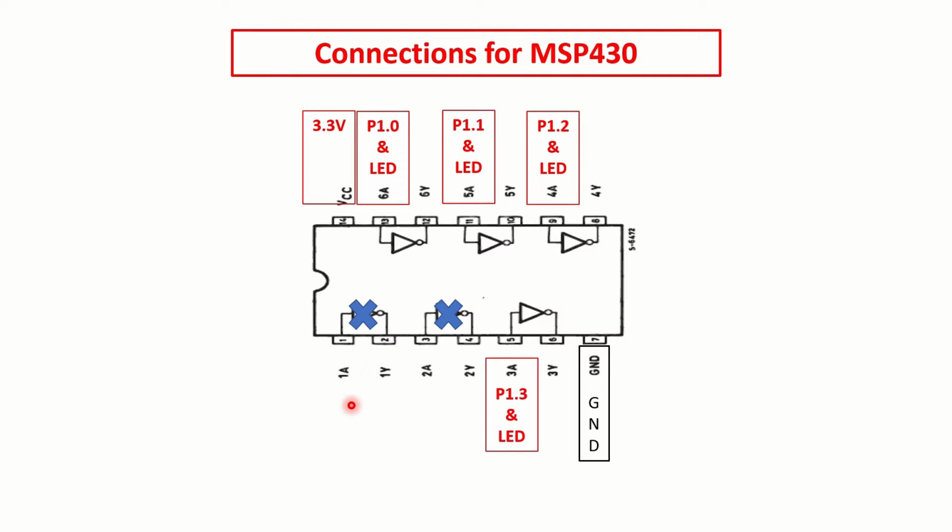I'll be connecting the 4 pins of the P1 port as seen in the diagram. At the same time, I'll be connecting 4 red LEDs in order to observe their status. And I'll be connecting 4 green LEDs to the outputs to observe their status. Now let's open Code Composer Studio and create examples to better understand this logic gate.